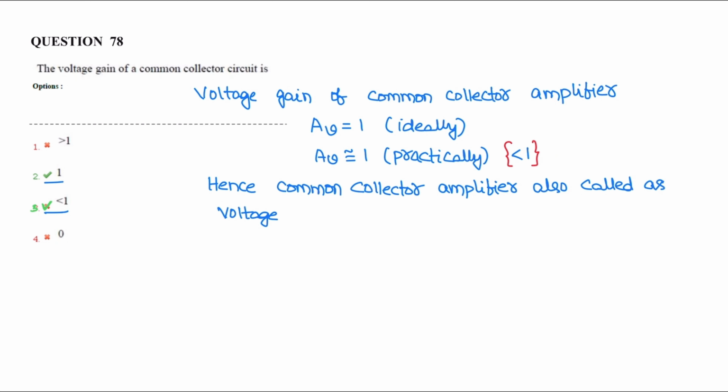The feedback network is connected in parallel at the input of forward path network. So if it is connected in parallel at the input, it implies current mixing or shunt mixing. This is a feedback network connected in parallel to the output, connected in parallel with the input.